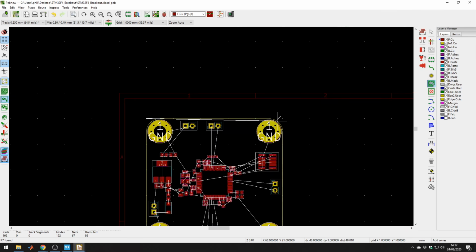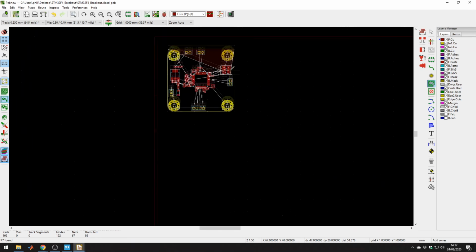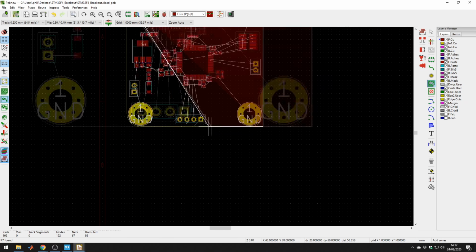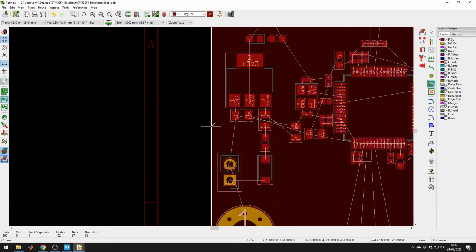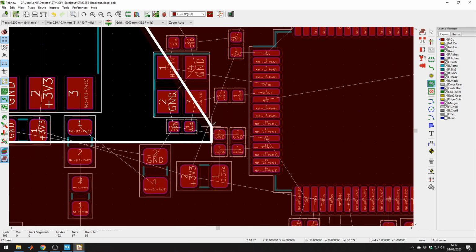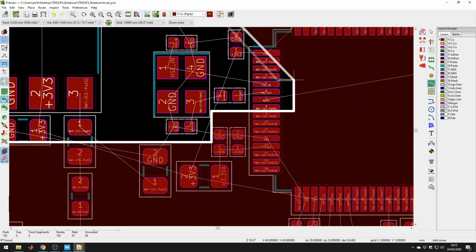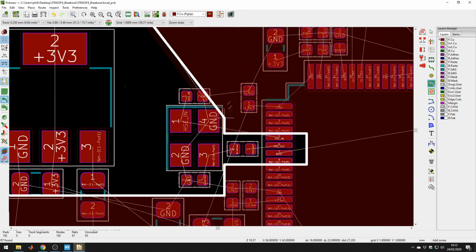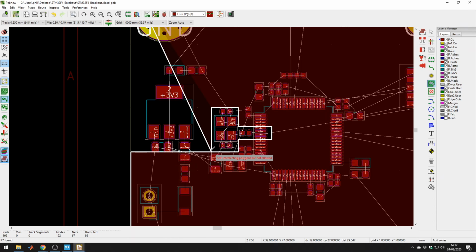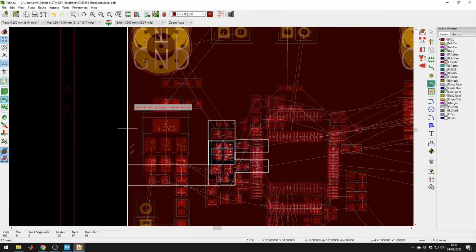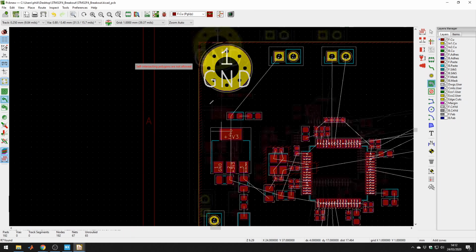And let's start tracing. There we go, go around the world, like that. Now, we're coming into the area where we need to be a bit more careful. So I will just be going up here, then I'll be going to the right. Again, this is a rough outline. So I want to stay clear of the crystal parts, which includes the pads going into the microcontroller, going around the crystal, closing it off, going here, and then closing the copper pour.